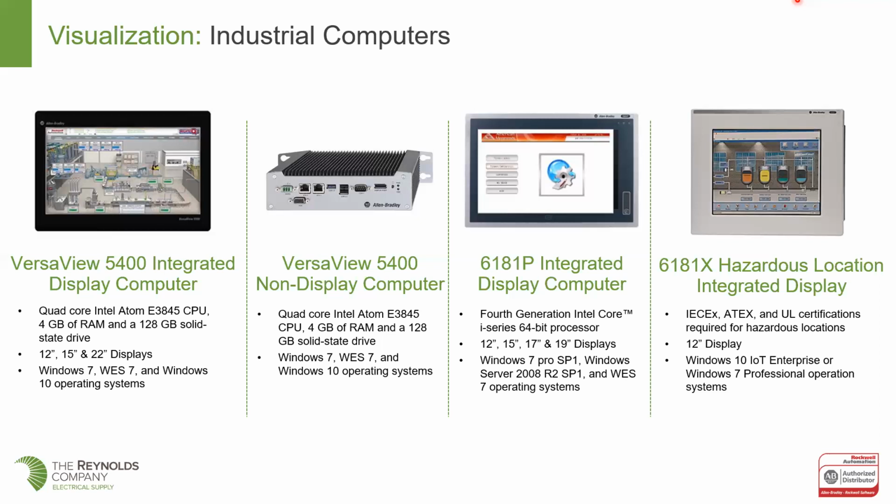The issue with this right now is that it's a kind of mature product. It still is limited to a 12-inch display. So I just want to make everyone aware of that. We do have another solution for it. If we need something for Class 1 Div 2 and need to go larger, we can always use a Class 1 Div 2 separate display and a Class 1 Div 2 shoebox computer. That would probably be our solution for that.